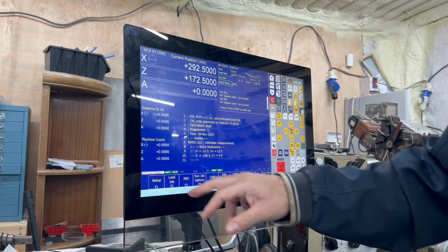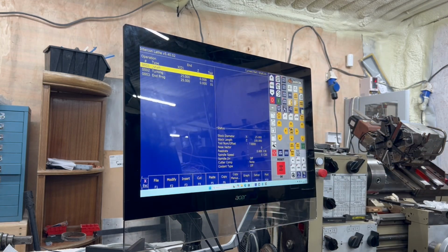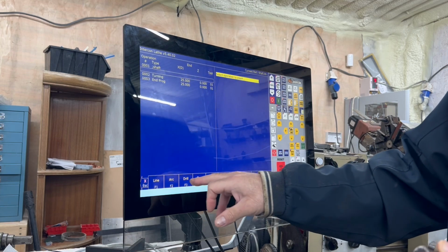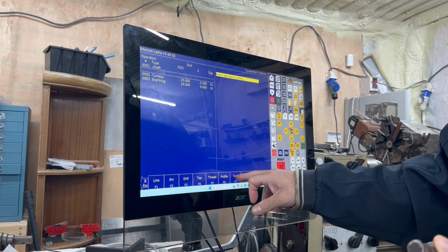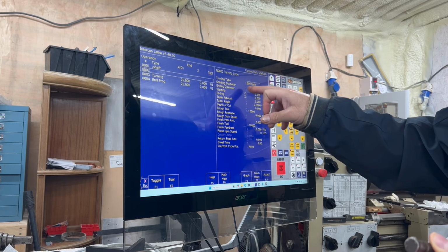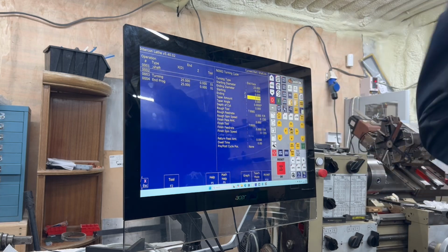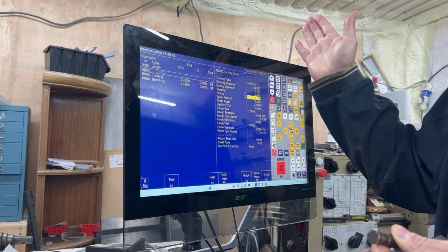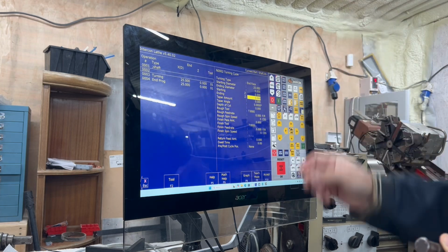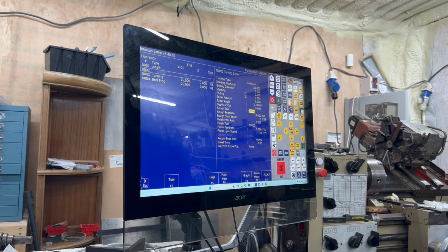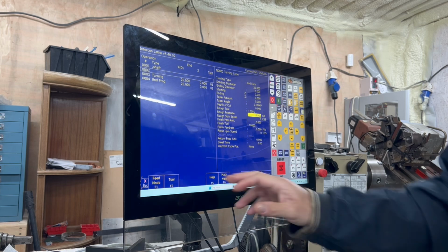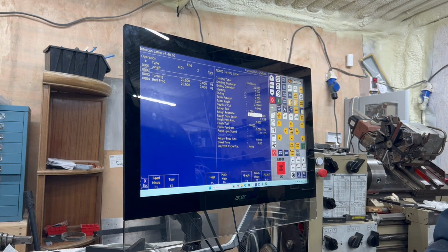Now what I didn't do is I didn't do a facing operation. So let's go back to CAM. Now what I can do is I can just insert a turn, and I can just go click there and go end face. Starting diameter 25. Ending diameter 0. Starting there. And what we can do is I'm just going to do 0, 0. So I'm going to do the part offset to basically just take the edge of the tool off. I'm going to do tool 1, 1, feed mode, do 50 there and do 2000 there.